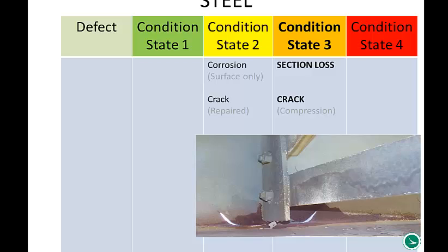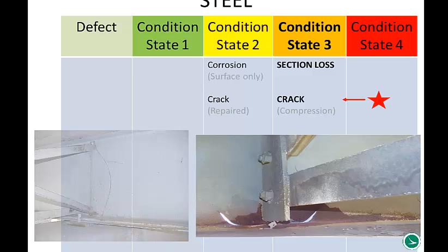Now you do have cracks in the tension zones. Condition state 4 is the place those should go. And again, an analysis can prove otherwise, but largely those would likely stay in 4 until a repair was made. Whether the crack is all the way through the beam, eliminating that load path, or in the tension zone, those are going to go into condition state 4.